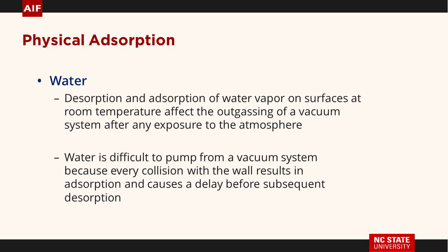What's the problem with water? Its sticking coefficient is essentially 1. So I've opened the chamber, I've got the water in there, and every time a water molecule hits somewhere, it sticks. This is why you see people baking systems above the boiling temperature, above 100 C, and then you can pump it out more quickly. That's something we'll dwell on when we talk about other issues.